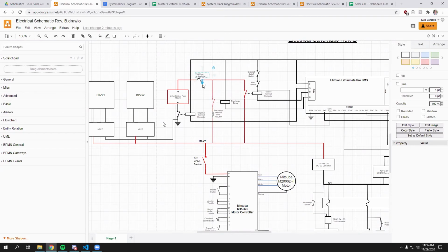Contrast that with a slow acting fuse: maybe you can have a lot of transients if your power signal looks something like this, and a lot of times it goes above 70 amps, you would probably want a slower acting fuse so that it wouldn't break immediately.